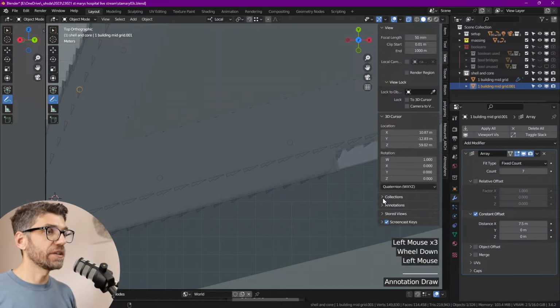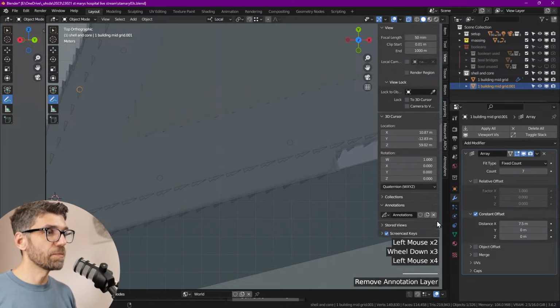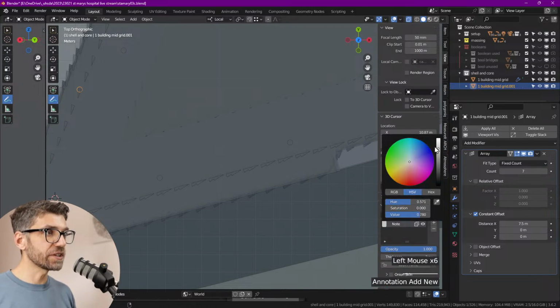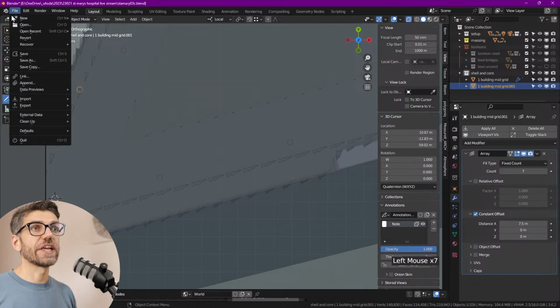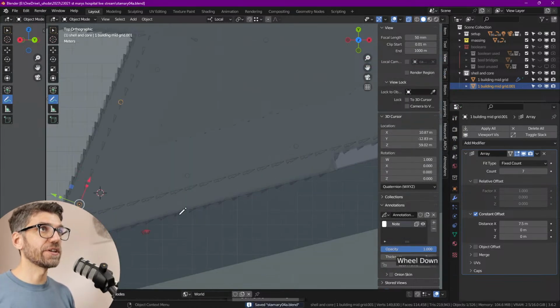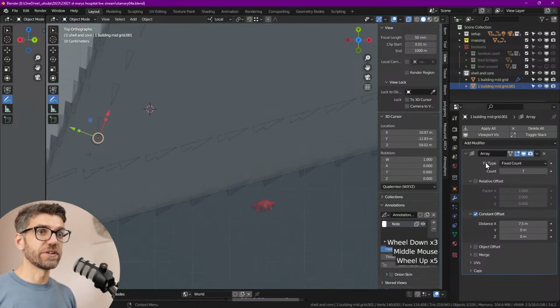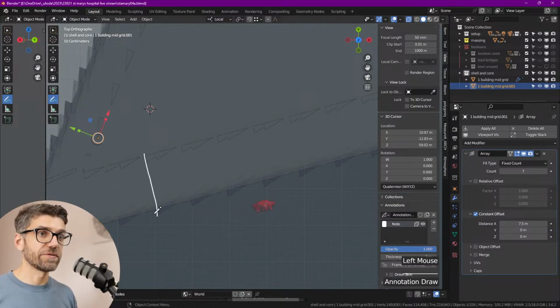However, that cantilever has to be a very, very small distance. Usually it should be less than 2 meters. If it's more than 2 meters, then we have a problem. So we have to be a bit careful on that. I'm just saving the file here so we make sure that we've got the right thing. So we have to check what this distance is, because that's going to make a big difference to us if that distance is more than it should be.